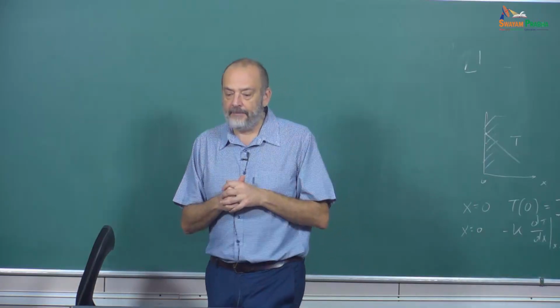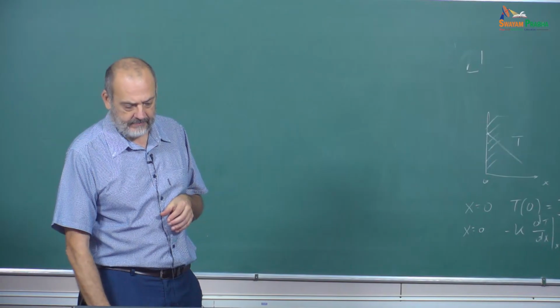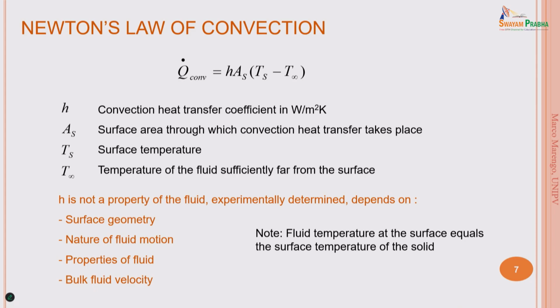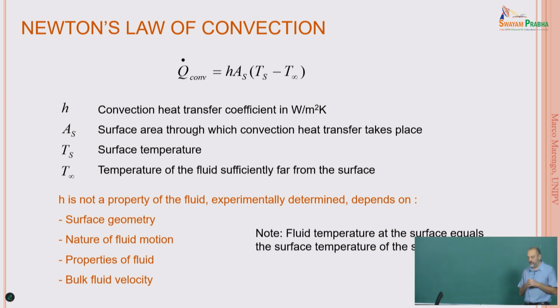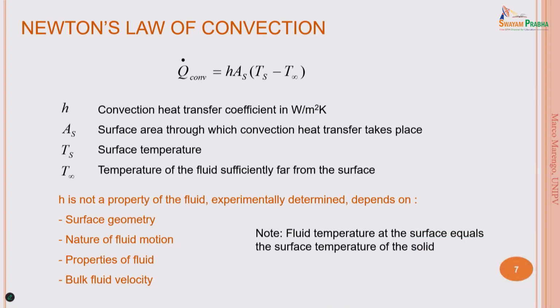In order to deal with this very complex situation, we can use Newton's law of convection, which is in fact a simple law, but all the difficulties and complexities are inside the h. So the trick is to know how much is h, also for multi-phase flows. The rest is almost obvious now. Of course, not at the time of Newton, but now, yes.